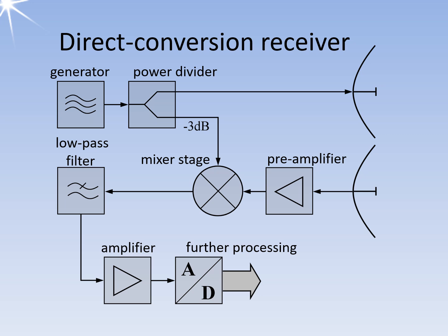The simplest and most affordable radar modules utilize a direct conversion receiver. The high-frequency received signal is directly converted into a low-frequency baseband signal in this setup. This conversion occurs in a mixer, which uses a portion of the transmitted power as a reference for the incoming signal. The output of the mixer reflects only the Doppler frequency. Mixers typically require a minimum amount of RF power at the input to function properly with the local oscillator frequency. As a result, the transmitter must be capable of supplying twice the minimum required power.